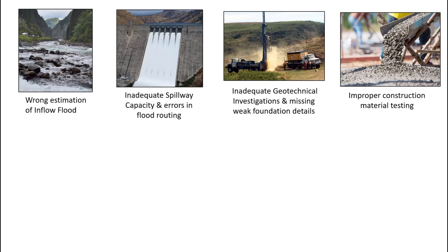failures. There are certain soils which are soluble in water and some are weak for certain minerals in water. Concrete structures get damaged due to presence of some acid-forming minerals and so on. For an earth dam there are different types of zones and for each zone the type of material is different. We use clay in the central portion, sandy material as filter. So material testing has its own importance in dam engineering.